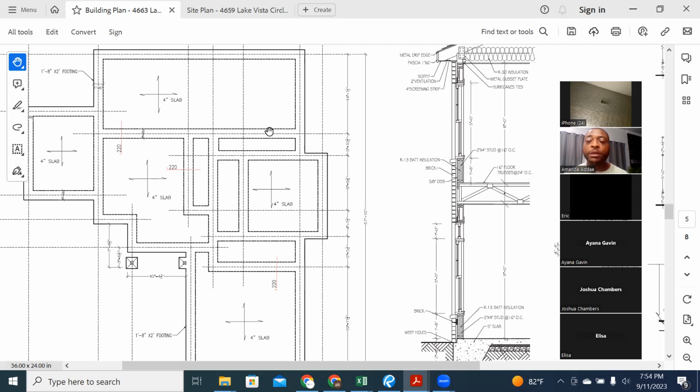What happens is then you put the plastic inside. You can use the same 6 mil plastic that we use to cover the slab. They actually sell plastic that you can use for that. It's like a yellowish one that we usually buy. It's actually much thicker than the 6 mil. We lay it inside of that pit that we dig, and then the concrete people are supposed to wash out their concrete into that. At the end of the job, you have 2 options. You can dig it up and haul it out, or you can cover it with dirt and do your landscape.